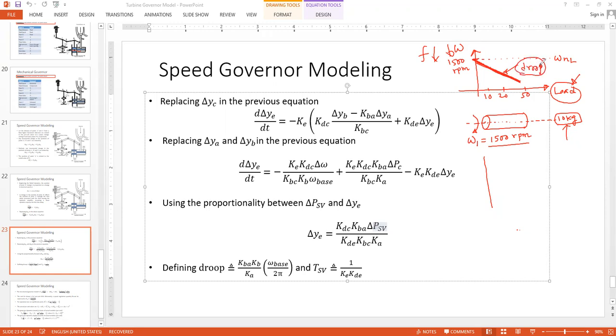Now in terms of a generator, what is the case? Again, if you are not providing any change, any control at the generator input side through the mechanical input, you are not changing any mechanical input to the system. Always we are going back to the simple equation: PM minus PE, 1 upon twice H, this is d omega by dt, right? This is the swing equation in per unit.